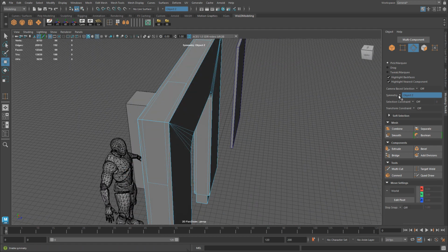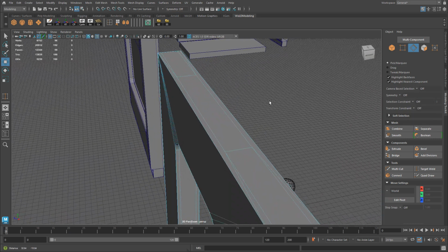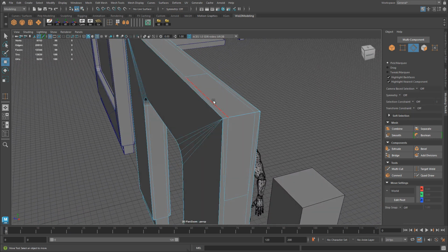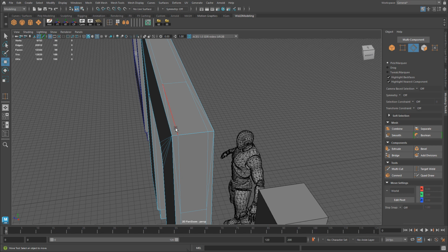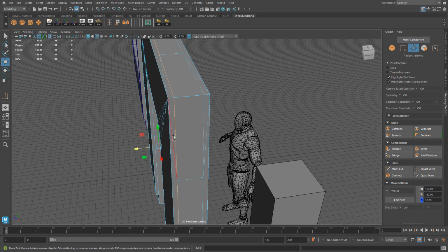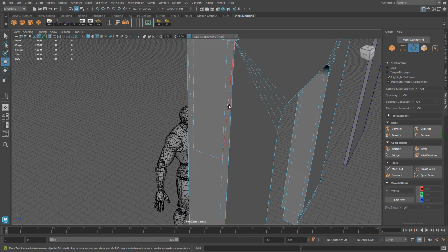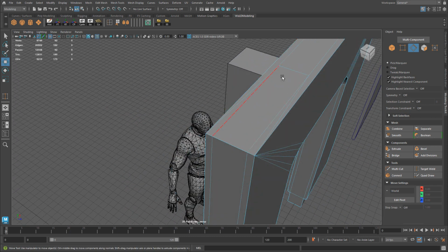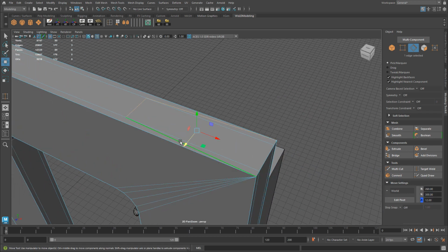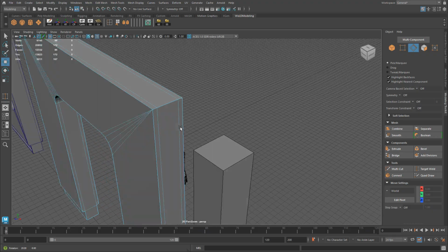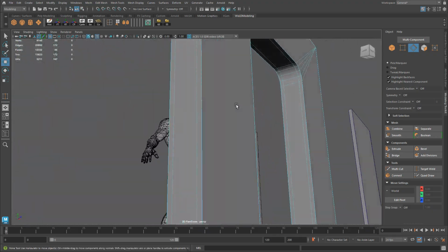So I'm going to disable object and turn off the symmetry. And I like to work in this one just a little bit more precise. I could have done it with symmetry mode, but that could have got me in trouble depending on what it selects. So it's just a little easier when I start. Just switch that off for this instance. So I only have 3 edges selected, so I'm going to hit Control Delete to remove that. Again, Control Delete will make sure that you are deleting floating verts. Very important that you press Control Delete so you don't leave those stray vertices on edges left behind. Control Delete. That's done. Let's take a look at the bottom. If the grid gets in the way, just turn that off.